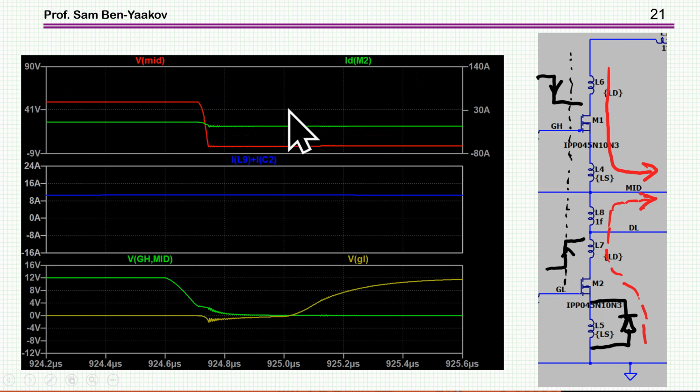Now, up to now, we talked about the worst case. Now, let's just have a glimpse at the case which is the best part of the switching, and that is when we have the current passing through the transistor, the upper transistor, and we turn the transistor off. Then there is a natural commutation of the voltage here until this diode is conducting, and only then we turn on the transistor in what you might call zero voltage switching.